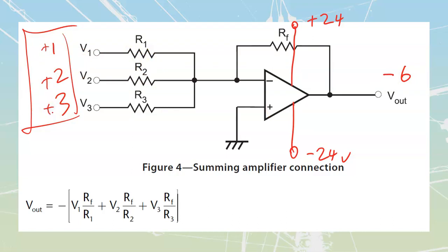It's useful if I have just 3 different values that I'm reading from something and I need to know the sum, particularly if you're looking at doing something like weighting, right? This might be attached to a scale, this might be attached to a scale, our outputs are always going to be in a voltage. This is that whole Wheatstone bridge thing you covered in 1st or 2nd year.